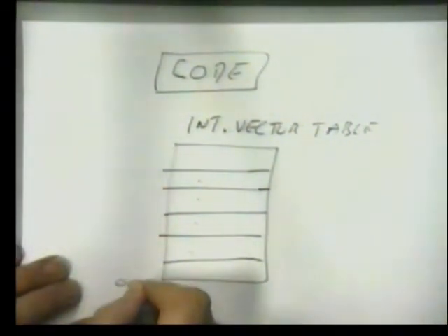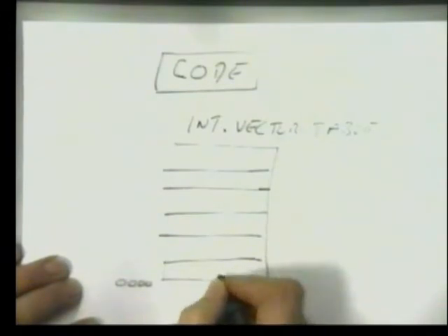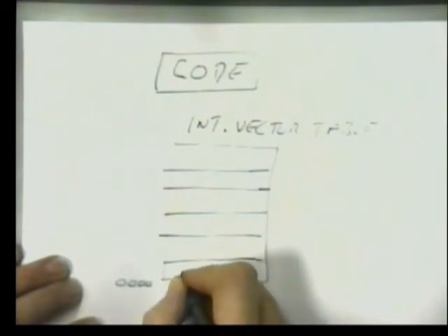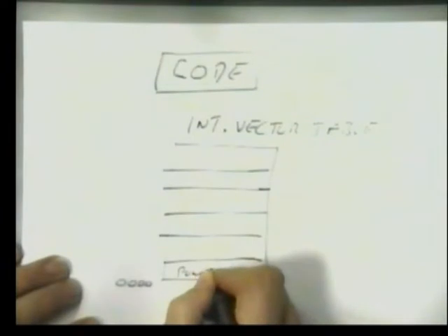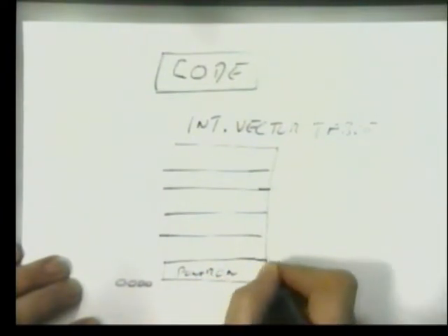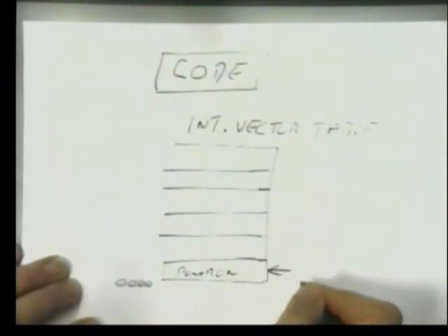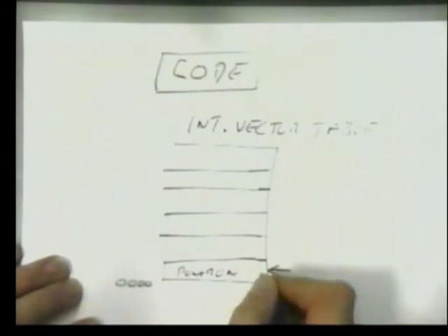If this was an Intel processor, it would be down the bottom at location 0. And that is the power on reset. It's always there. It's always in the same place. Every Intel processor, from the humblest microcontroller, the 8048, all the way through to the Pentium, the power on reset vector is always the first 2 bytes in the memory map. It's always down the bottom of that location 0, without fail.